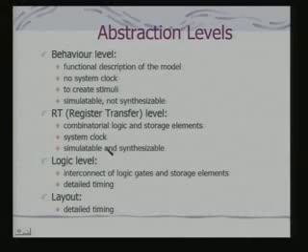So if you look at it from that point of view, your register level actually gives you a gate level or storage element level specification of the circuit, and obviously the clock is an important component. So this register level specification gives you a simulatable as well as synthesizable specification.